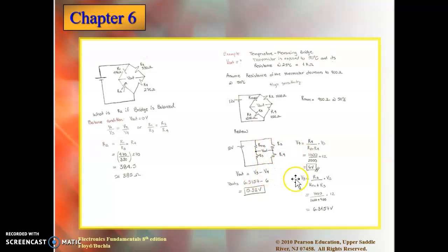Knowing that, I can use my knowledge of circuit analysis from chapter 3 and chapter 4, where I analyzed series circuits and parallel circuits. What I have here is a series circuit. So I know that from here to here, I have 12 volts because this is across the voltage source. And then I'm going to split these 12 volts across these two resistors. So I can find V3 using the voltage divider. The voltage divider says that if I'm interested in V3, I'm going to multiply the resistor that I'm interested in by the source divided by the sum of the branch.